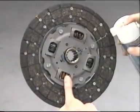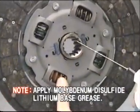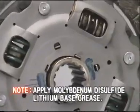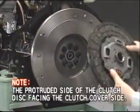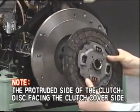After necessary treatments, install the clutch disc and the cover. Apply a coat of molybdenum disulfide lithium base grease on the clutch disc splines. Be sure to set the clutch disc with its protruded side facing the clutch cover side.